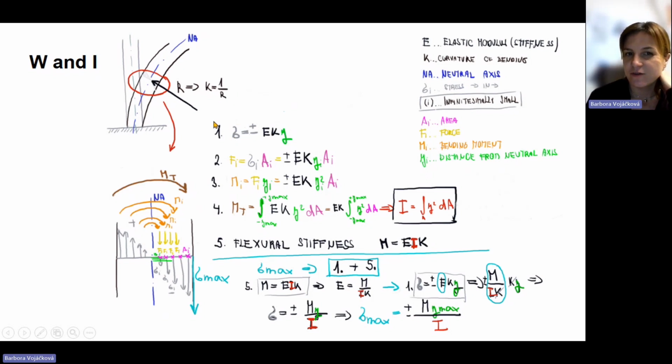And this curvature of bending, the letter kappa, we use in the calculation of the stress in the tree stem. You can see in the first equation that the stress is basically calculated from the stiffness of the material, which we describe as the elastic modulus. This is multiplied by the curvature of the bending stem. And there is also the importance of the distance in the cross-section area of the stem. So the small epsilon letter is the marking for the distance from the neutral axis.